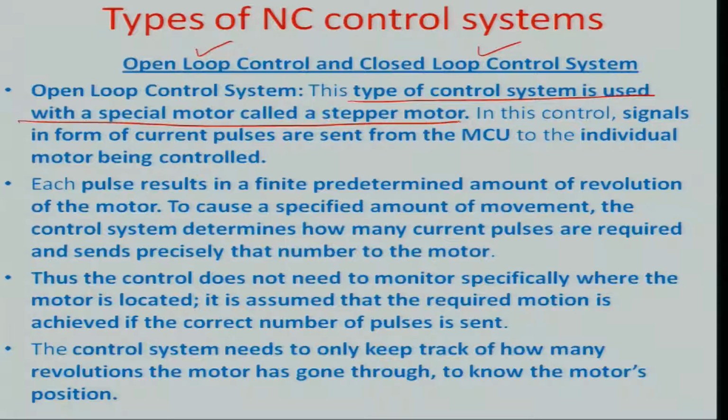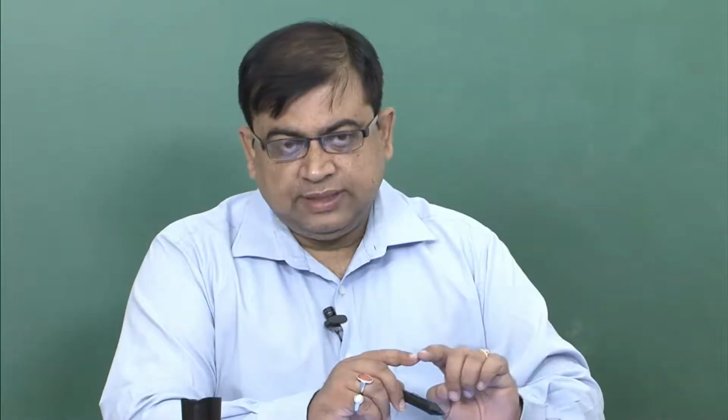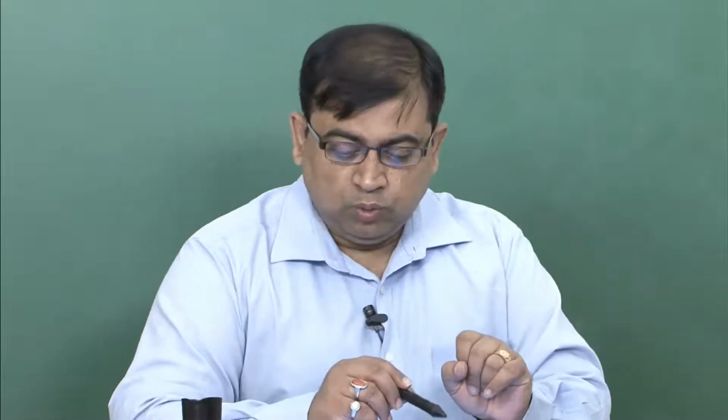Obviously the stepper motor is very accurate, so you can actually know how much it has proceeded linearly by means of how many pulses have been provided to the stepper, because the stepper actually turns exactly so many degrees of rotation after one voltage pulse has been given. So it is a very correctly controlled, very precisely controlled motoring system.